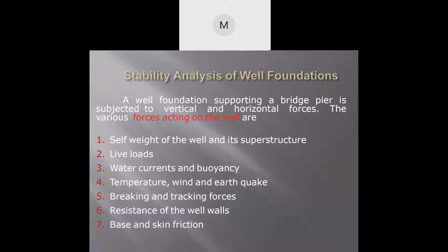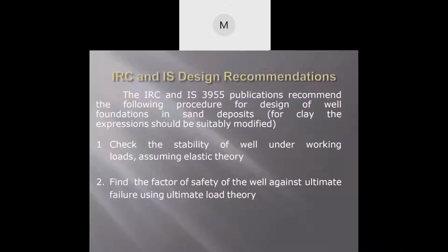The various forces acting on the well are self weight of the well and the superstructure, then live loads, then water currents and buoyancy, then temperature, wind and earthquake, then braking and tractive forces, resistance of the well walls, base and skin friction. Now, as per IRC and IS 3955, the following design procedures are recommended.